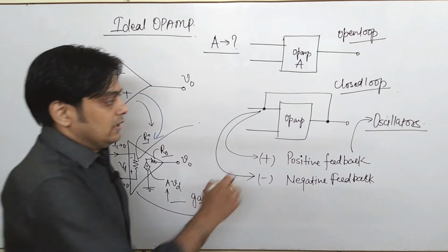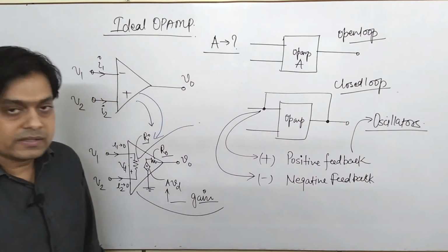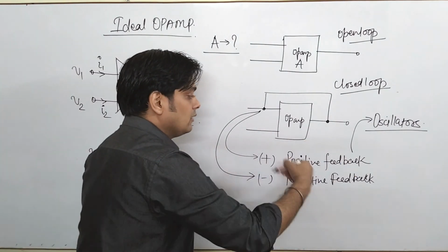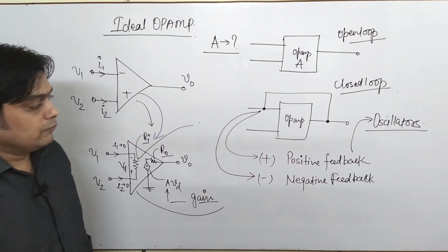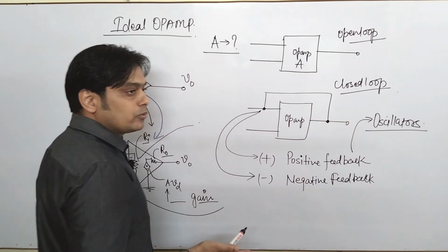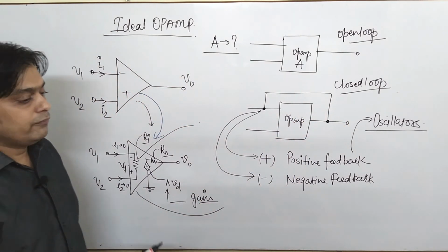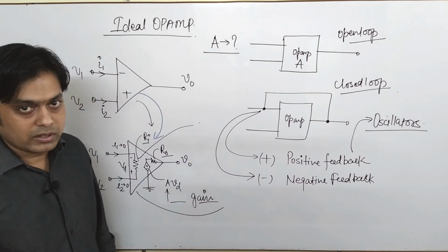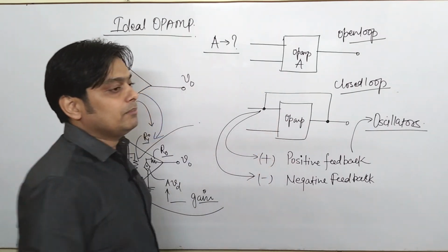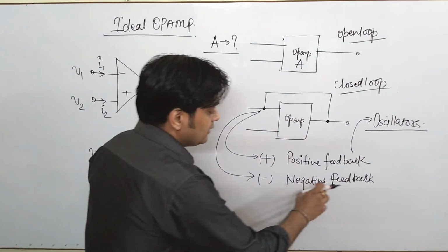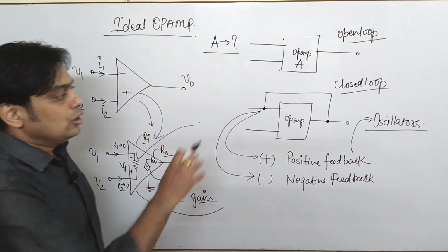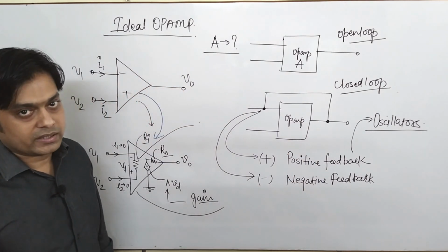Oscillators are the electronic units in which the oscillations get increased depending upon the value of feedback applied. Positive means whatever signal is coming here is again added into it, and you get an output. So oscillators are the units in which you will find very high oscillations. Oscillators basically use positive feedback, but when you are talking about an operational amplifier or any other class of amplifier, you generally use negative feedback, and negative feedback is specifically used to stabilize the output parameter.